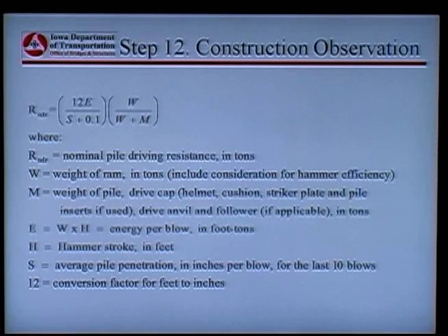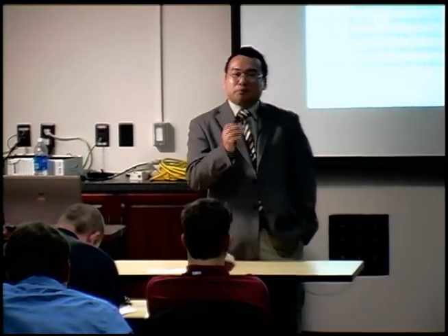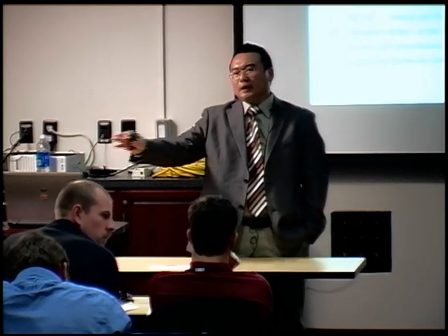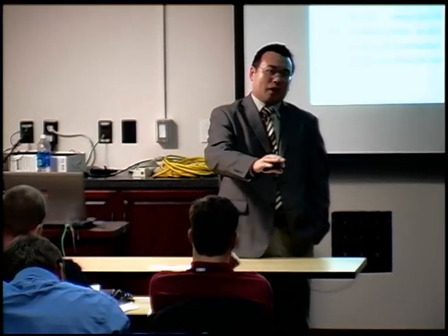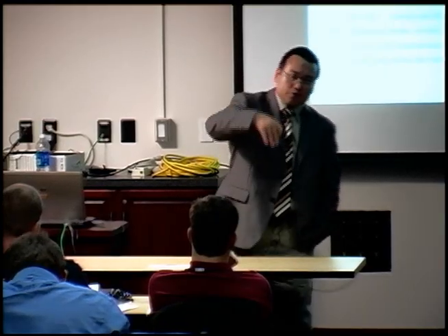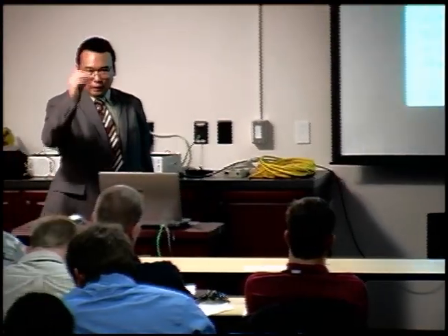Again, if the retap driving resistance is smaller than the target resistance, you have two options, as what Don has mentioned earlier. Either you extend the pile further down, or you perform a much more complex analysis like using PDA, CAPWAP, or perform a static load test to verify the pile capacity. All right? And that hopefully will be able to solve the problem and achieve the pile resistance with the options of driving further down or performing a more complex or more robust analysis.